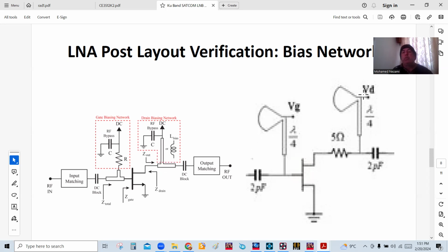So what we've turned to is something called radial open stubs. And now, again, what this does is we use radial stubs in conjunction with a quarter wave section to pass the DC, or insert the DC, into the drain and into the gate. And the way this operates, I'll show you in a minute, is that we assume the following. A quarter wave radial stub, okay, is the same as a regular rectangular open stub. The input impedance of it, because it's open, is really short.